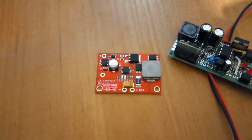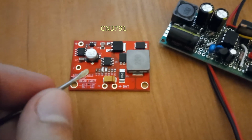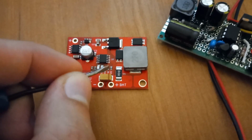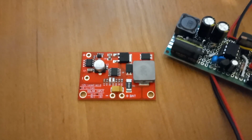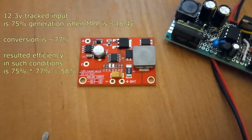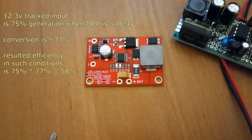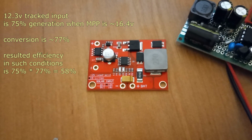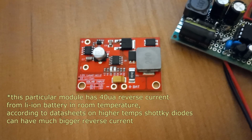A few more words about this device. It uses the CN3791 chip and it tracks a fixed input voltage of 12.3 volts defined by this voltage divider of these two resistors. So its generation efficiency is pretty low, like some 75%, and its tested conversion efficiency is also low, around 77% in my tests. It also suffers because of extra Schottky diodes they put in to avoid reverse current, which isn't good for reverse current protection, by the way.